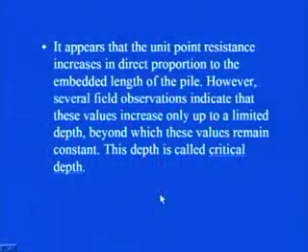It appears that the unit point resistance increases in direct proportion to the embedded length of the pile, because you see that effective stress, that is sigma bar into Nq, is your unit point resistance. In the absence of any water table, what will happen? Your sigma prime will become equal to the total stress, and that total stress we can write down as gamma